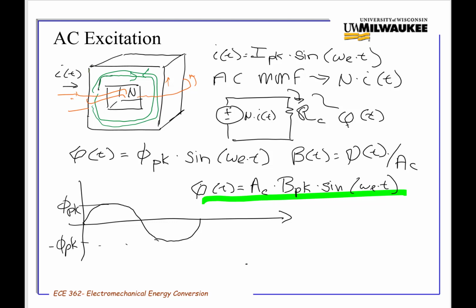But this is just me wrapping my coil around it and figuring out where my two ends are and how my voltage is going to be oriented. So because of Faraday's law, you can find a voltage across a second open circuited winding. And in a sense, what we're showing right here is the introduction to the transformer section. This is your very simple open circuited transformer as well.